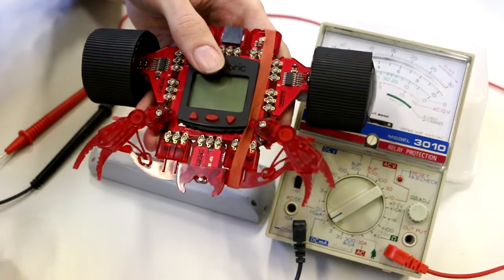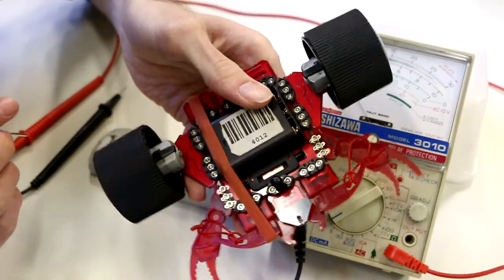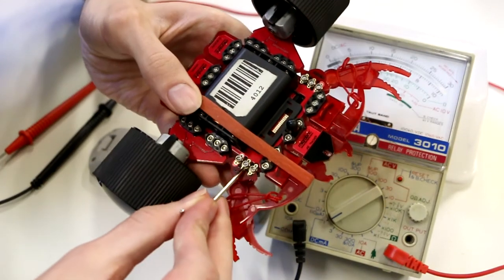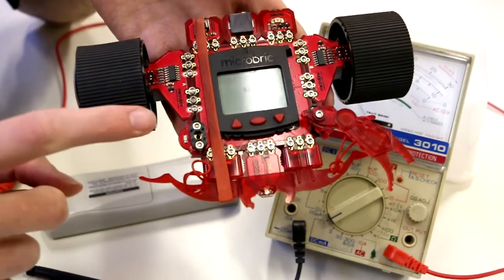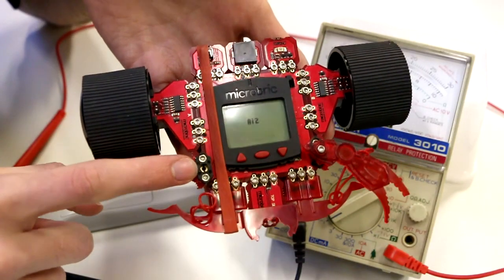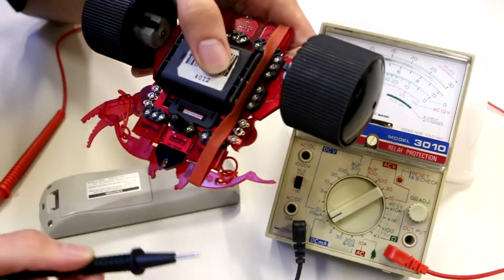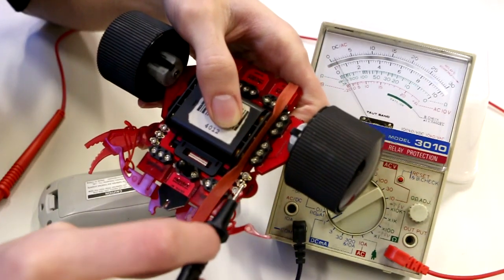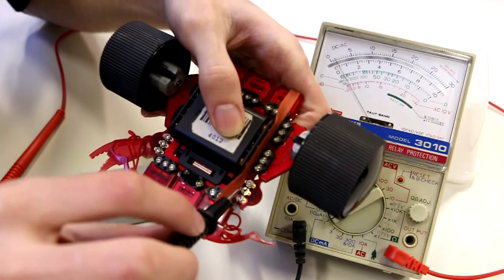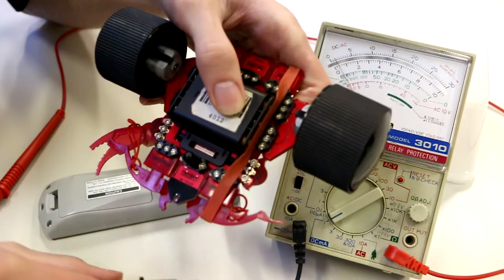To break the circuit, so to speak, you want to turn the robot over, and we're going to remove the middle screw here of the LED module. Now that the screw and front claw are removed, we can take our current reading. What you want to do is take the black probe and put it on the left hand side here of the LED module in the middle, and our red probe will be on the opposite side of that, on the right hand side where the motherboard is.